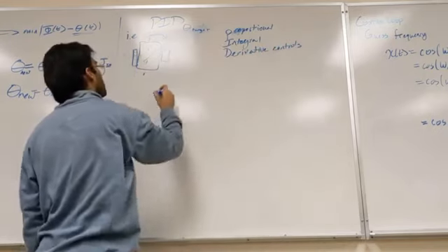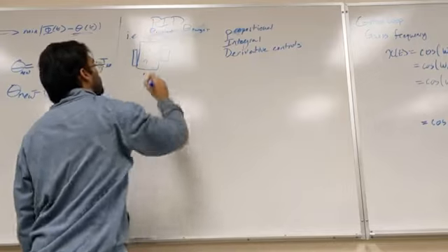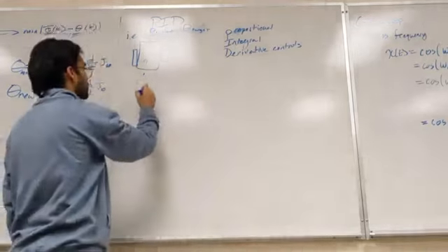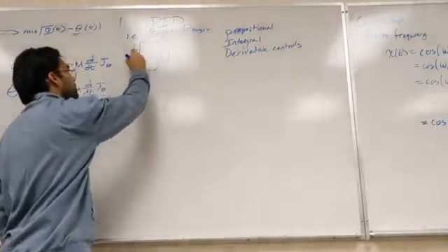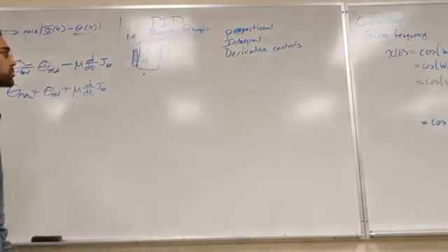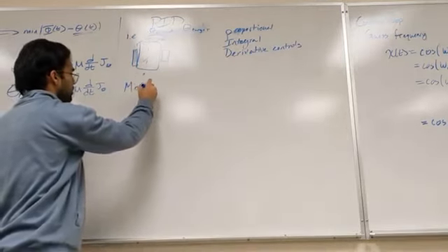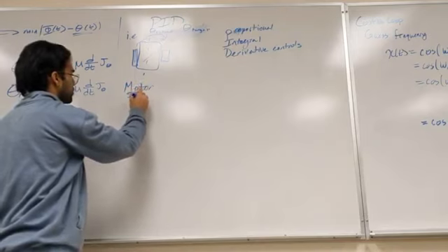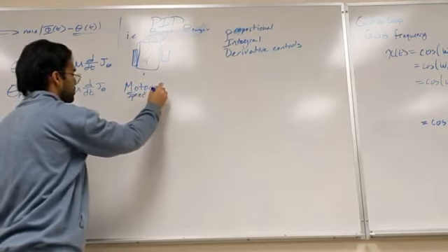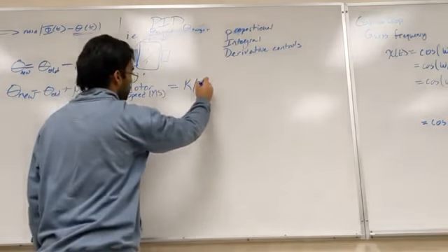Proportional would be like, okay, here's my current angle, and I need to turn these wheels such that I turn to that angle. So we'll set the motor speed, we'll call it ms, equal to some proportion times how much we're off.